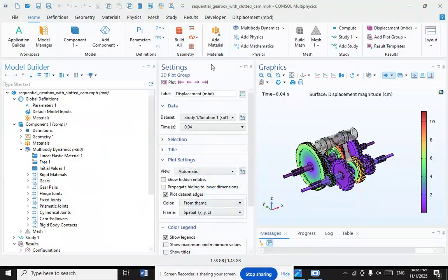A sequential manual transmission is not to be confused with the pneumatic sequential shifting function, sometimes fitted to hydraulic automatic transmissions marketed with trims such as Tiptronic or Sport Shift. This function allows the driver to select the previous or next gear through the use of buttons or a lever usually near the gear shifter or on the steering wheel. However, the mechanics of the transmission are unrelated to a true sequential manual transmission.